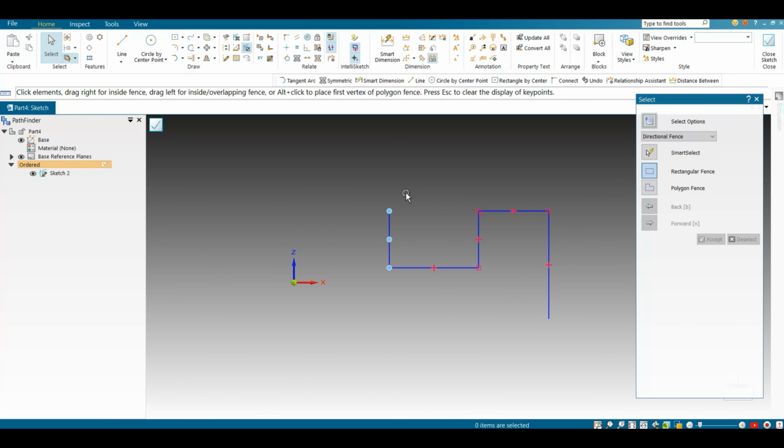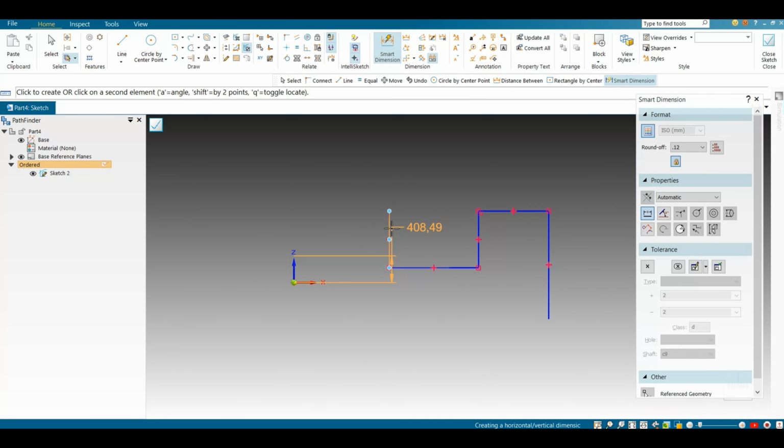For example, if I want to show some dimension with reference to this Z axis, this is the particular cross section I'm going to revolve. This is its dimension from this Z axis, which is 1400 something, but I want to make it a symmetric dimension, which means I want to make it double.